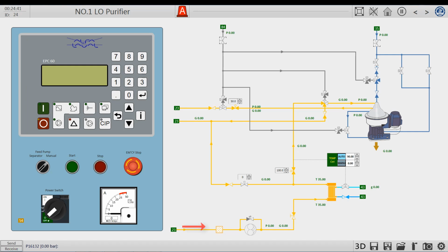The inlet line is a bottom line. Through a heater, the steam heating line provides heated steam to maintain the oil temperature before entering the machine and improve the separation effect. Here the automatic setting is 90 degrees Celsius. Through this feed line, lubricating oil enters the oil separator.